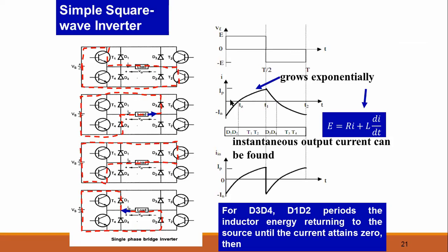Suppose you provide a pulse over here, but there is no need to turn on the thyristor over here as no current is provided to the thyristor, so the thyristor will remain turned off. But if we turn on the thyristor over here, the waveform shape will start from here.